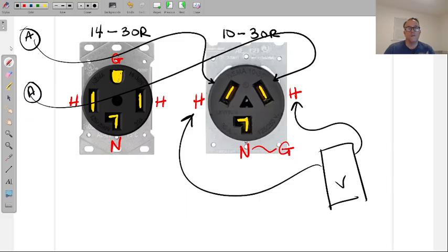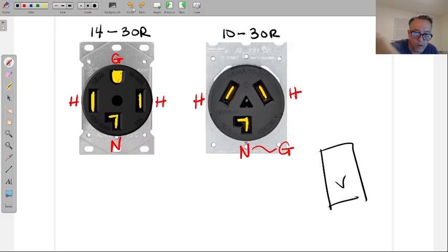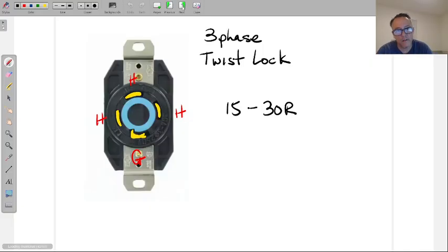So all of these things have to be done anytime you check an outlet. I check between the 2 hots. If it says 0, don't just assume I got no power. It could be another weirder problem. Check now between the hot and the neutral, see if you're getting 120. And don't go, oh, I'm not getting 120, definitely the breaker. No, now check between the other hot and the other neutral. Always see everything. Don't walk away not having numbers to all of it. I never assume anything.